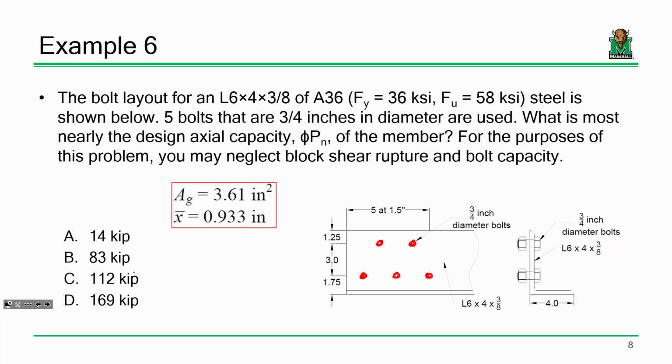So what, y'all steel design folks, what pops out to you? Stagger factors, because the bolt pattern is staggered. Your failure path is going to look something about like that. Because if I take this angle and I pull on it with some force P, it's not going to just go straight through. It's going to fail along the bolt lines. Y'all remember that? So in order to do that, you need all the dimensions, you need the gauge factors. Then this is an angle. Angle properties aren't in the manual, so you need AG and you need X bar.